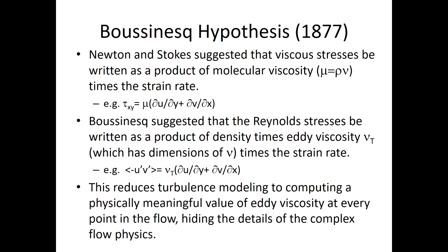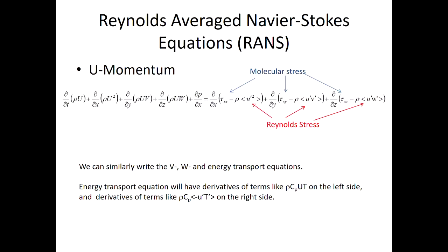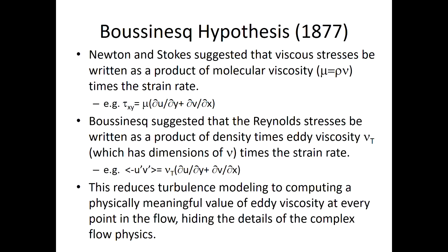So there used to be a rho here. You can put a rho here. If you look up here, there's a rho here, but rho is not physically known. We don't need to model it, so we are only modeling this part of it. That part is modeled as an eddy viscosity times velocity gradient. Molecular viscosity, eddy viscosity. Eddy viscosity, by the way, has the dimensions of meter squared over second, just like a kinematic viscosity, nu, has a meter squared over second type of unit.